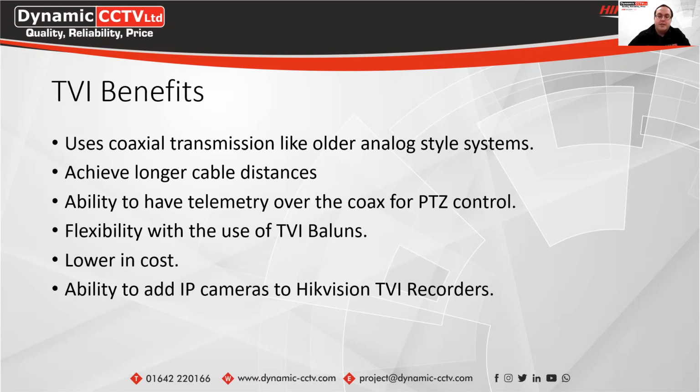A lot of old systems do use subpar quality cabling, whereas others don't. So it depends on the scenario that you're using it in, and also the cable runs that you're needing to achieve. Obviously, the higher quality cable that you use, the greater distances that you can achieve with TVI transmission. And with POC, that's limited to up to 200 meters from your DVR to your camera point. You can also generally achieve longer cable distances with standard TVI cameras, with some in the range on the low resolutions achieving up to 700 meter cabling distances.